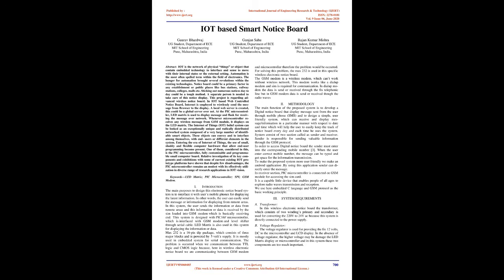In IoT-based web-controlled notice board, the Internet is employed to wirelessly send the message from a browser to the display. A local web server is created. This could be a global server over the net. At the PIC microcontroller, an LED matrix is used to display the message and Flask for receiving the message over the network. Whenever the microcontroller receives any wireless message from the GSM module, it displays it on the LED matrix.